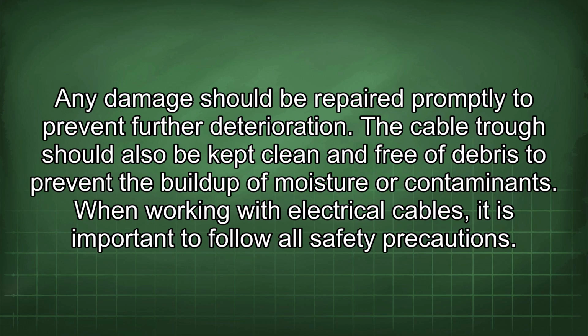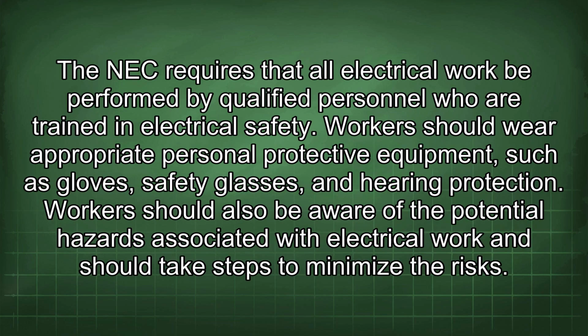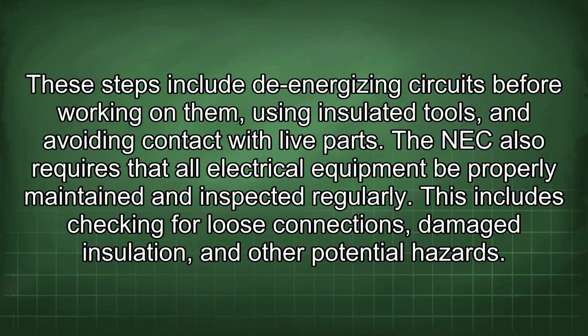When working with electrical cables, it is important to follow all safety precautions. The NEC requires that all electrical work be performed by qualified personnel who are trained in electrical safety. Workers should wear appropriate personal protective equipment such as gloves, safety glasses, and hearing protection. Workers should also be aware of the potential hazards associated with electrical work and should take steps to minimize the risks. These steps include de-energizing circuits before working on them, using insulated tools, and avoiding contact with live parts.